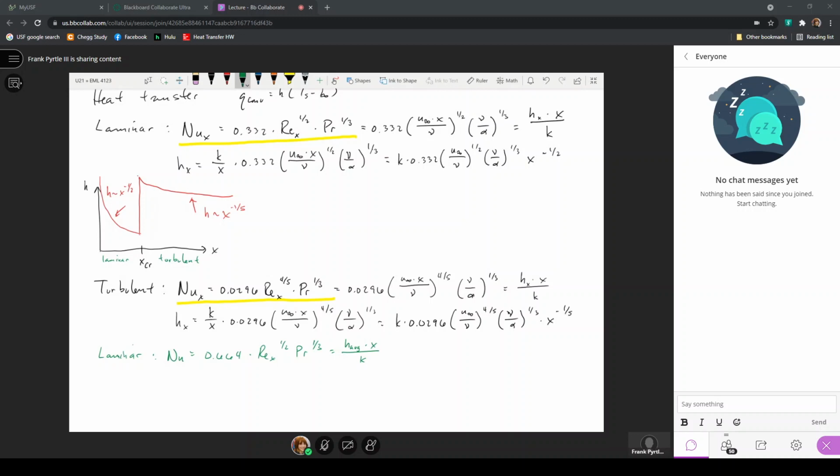So this is another reason that you want to be able to find the transition point, so you can determine what the length of the laminar region of flow over the plate is. The flow will always start out as laminar and have to transition from laminar to turbulent. The only time you're going to see turbulent flow over the entire plate is if there's a tripwire, which basically induces a rotation into the fluid before the fluid starts to move over the plate.